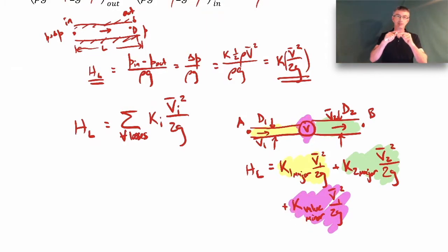That's because of the viscous effects and all the turns and movement of the fluid through the interior of the valve. Because there are velocity gradients in there, you get viscous effects. That dissipates energy, and so you need a little extra pressure to push through that valve. And the way we would find that loss coefficient for the valve is we would go to a table, which I'll talk about in a moment.